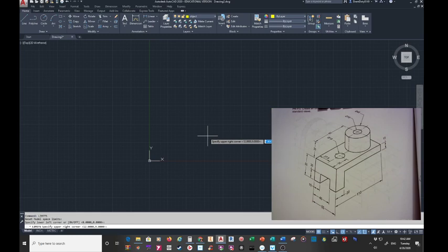So basically what I like to do is I just make a square. I just look at how wide are the views that I need. If you were to look at, and I don't know if it's going to pull it up or not, but it may show my mouse, it may not. But you'll see on the screen, it shows that it's 110 wide and it's 55 deep. Well, on your front view, you'll see the 110. The side view, which is going to be a right side view, even though it shows the left over here more so, you're going to do a right side view.